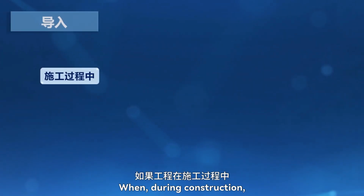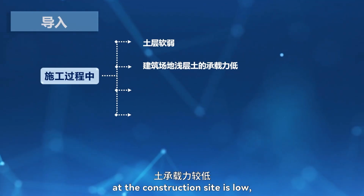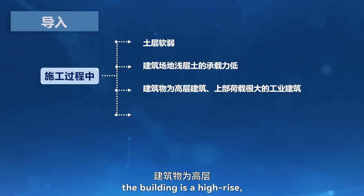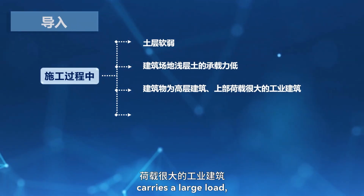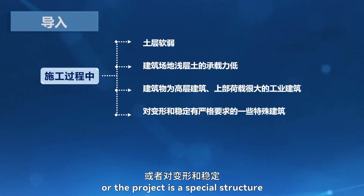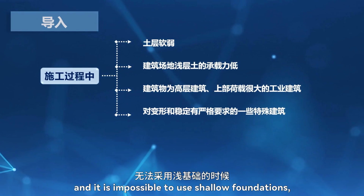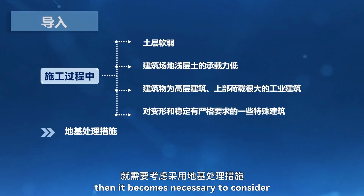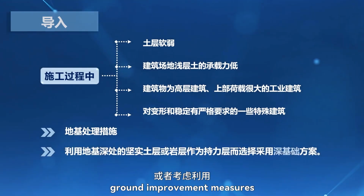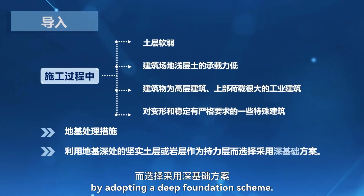When, during construction, the soil layer is weak, the shallow soil bearing capacity at the construction site is low, the building is a high rise, the upper structure of an industrial building carries a large load, or the project is a special structure with strict requirements for deformation and stability, and it is impossible to use shallow foundations, then it becomes necessary to consider ground improvement measures or to use deeper, stronger soil layers or rock strata as the bearing layer by adopting a deep foundation scheme.